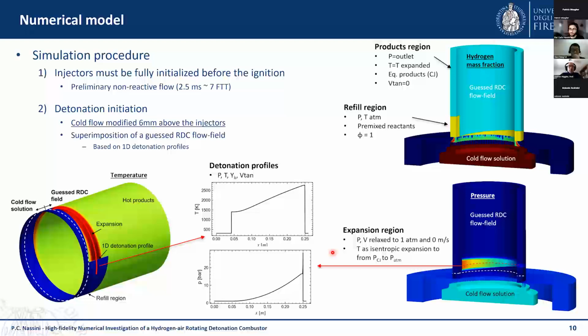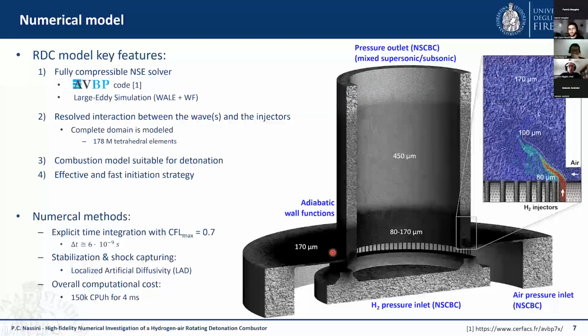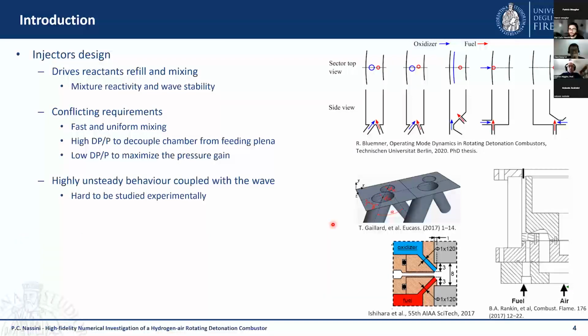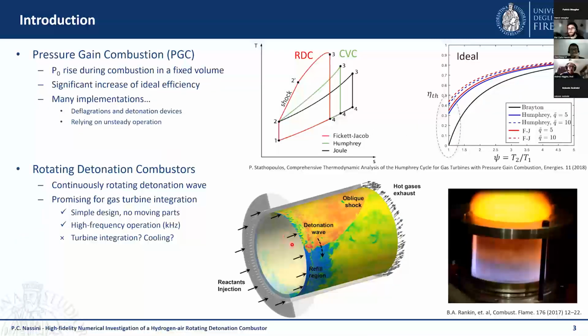In fact, a detonation wave is a very large generator of entropy and decreases total or stagnation pressure. In fact, total pressure varies inversely with entropy generation in a flow. So I'd like to understand what you meant when you said that using a detonation will result in an increase in total pressure.